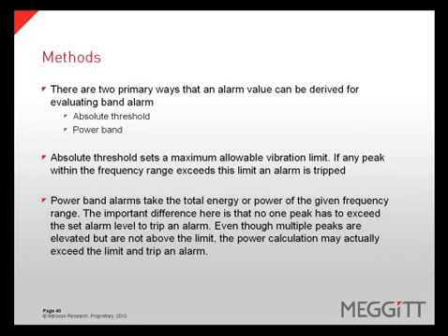This is particularly useful with faults like bearings, where the amplitude of each bearing defect harmonic may not be excessively high, but the number of harmonics can certainly be an indication of a more severe problem.